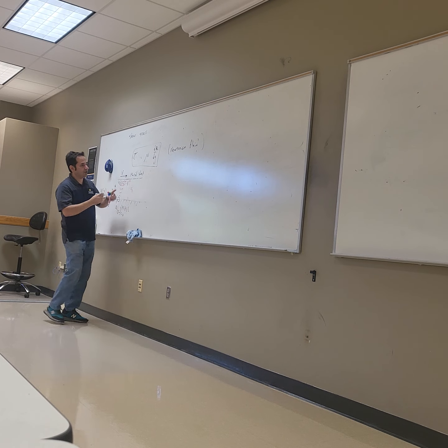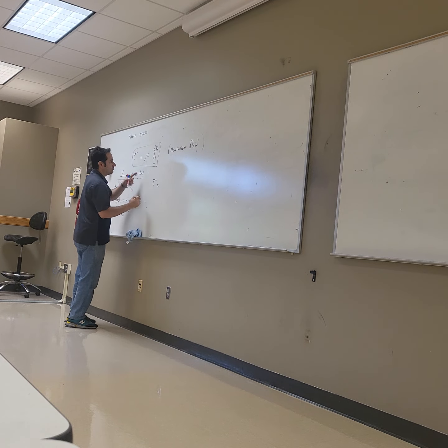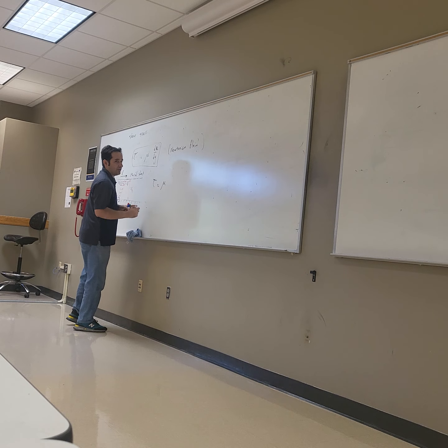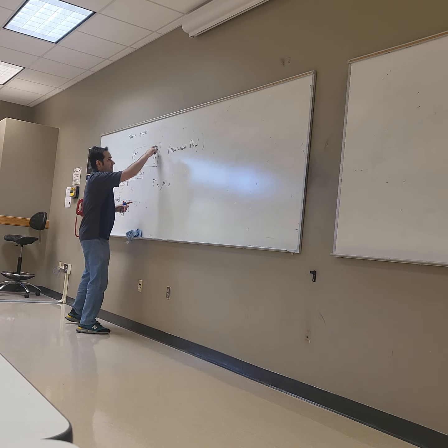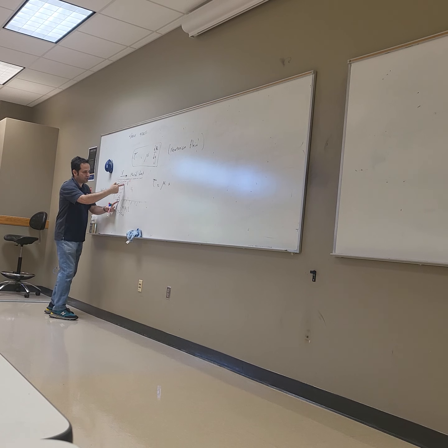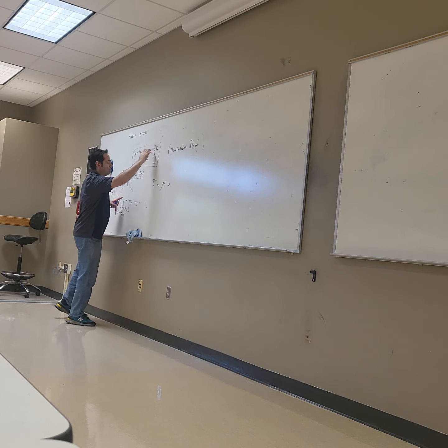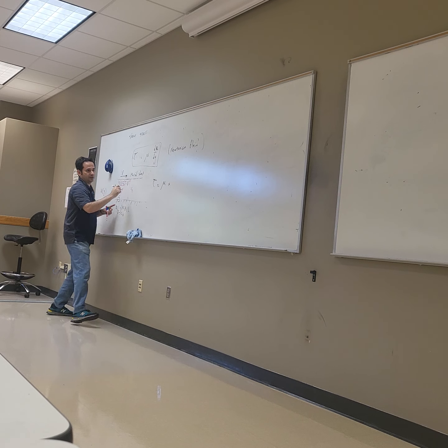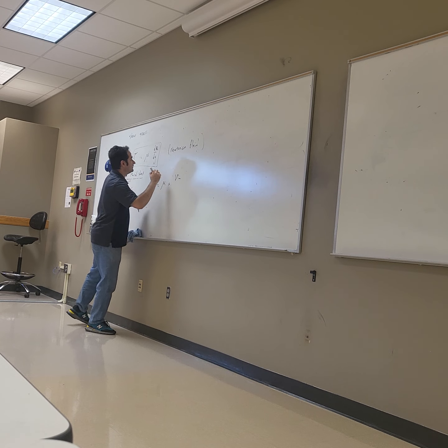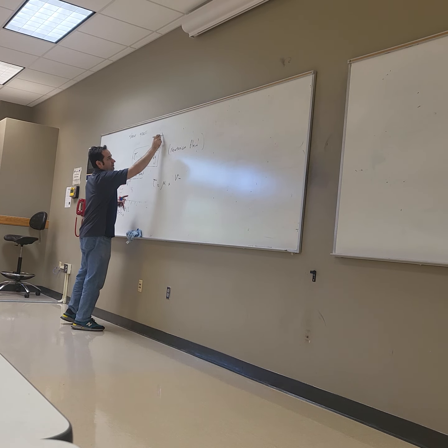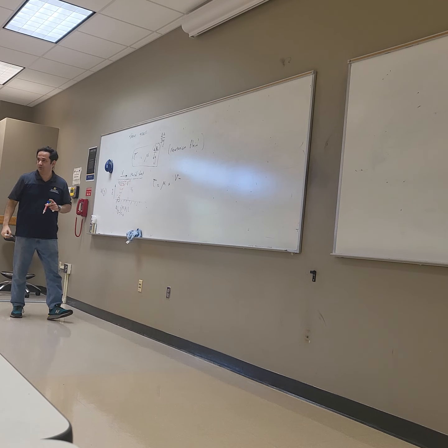In that case, I can write tau is equal to dynamic viscosity mu times the velocity difference. Look at the equation of this line. It's the velocity at y plus delta y minus the velocity at y, so you can write it as delta u over delta y, right? Can't you do that? You can.